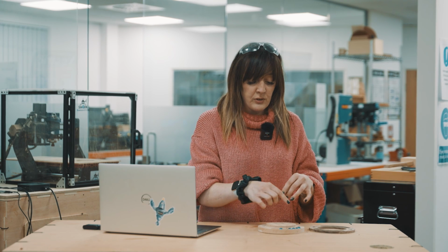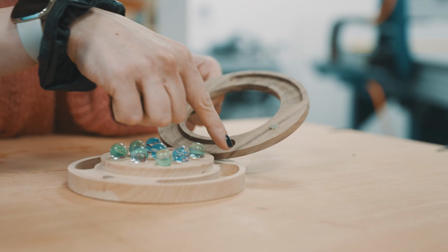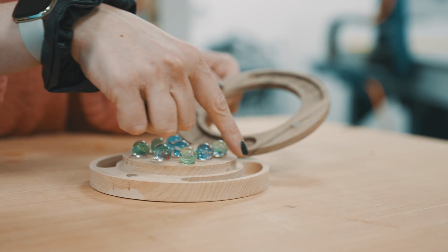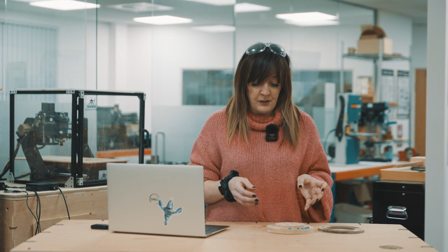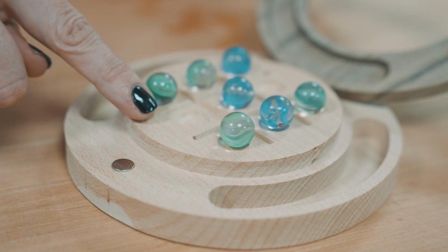We're going to be using 3 tools in total: an end mill to create pockets for channels, to hide away your marbles, for the profiles as well to cut the parts out. We're going to be looking at a round ball nose tool to create little divots for the actual game pad itself, where you can pop your marbles into position for the game.